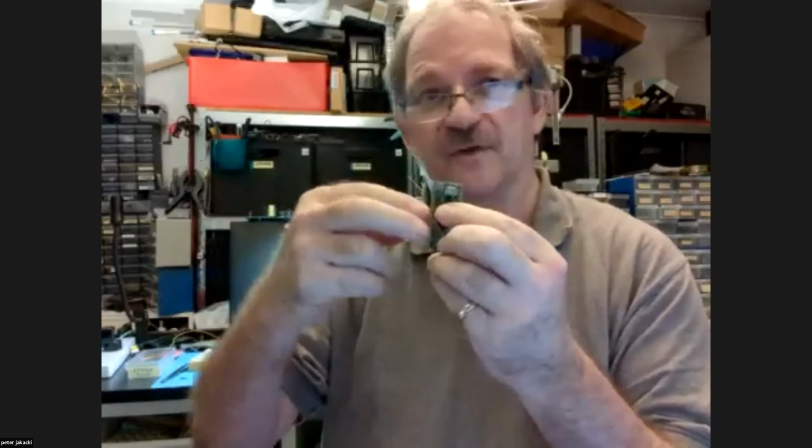Additional questions, comments? Yeah, Peter. Hey, Brad, I was just talking about extending the 16-bit address range. I do this on 32-bit processors. I've got the P2 8-core processor, but my Forth uses 16-bit address tokens. It's nice and compact. I don't want to go to 32 bits, but all I do is I just have a paging instruction code, one instruction code for the next page up to 64K, you know, page 1, page 2, etc. And it only flips that page for that call.